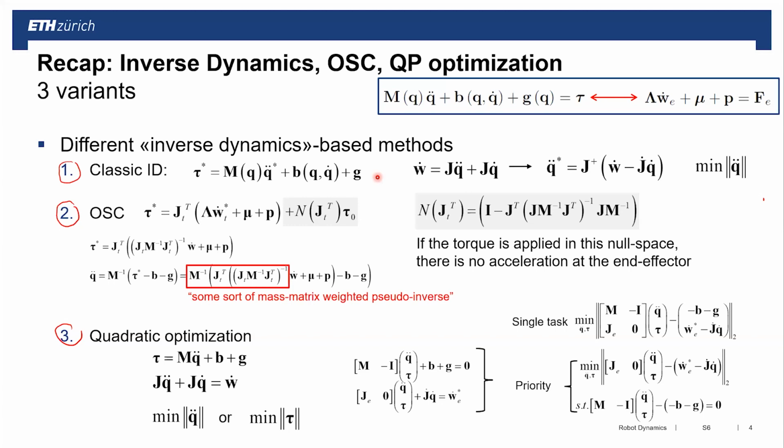Now, depending on the dimensionalities of the task description, of the number of degrees of freedom that we have, so how many Qs exist, this is in essence solving a minimization problem, saying: what torque do I need to apply to my robot in order to make it move such that my end effector follows a predefined end effector acceleration, which comes in here through an omega, a W dot desired, and which solution minimizes the total acceleration, or the least square solution in the acceleration.